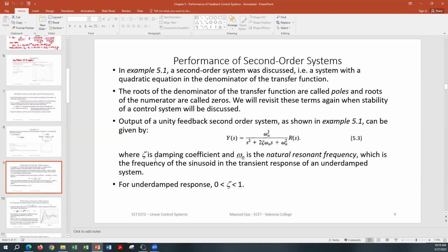So now we're going to look specifically at the second order system, and the second order underdamped system that is oscillatory in nature. And this is something we also discussed in chapter number 2. We did an example and we used one of the transform pairs for the second order system to write down the time domain nature of the second order system with that pair.